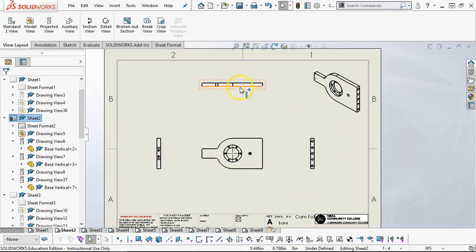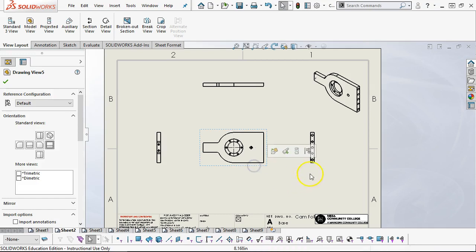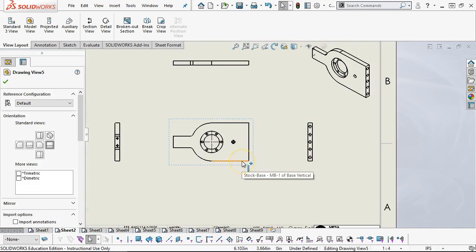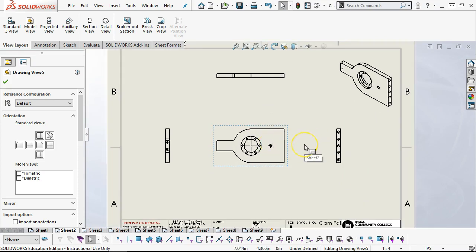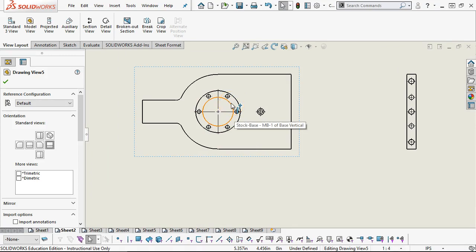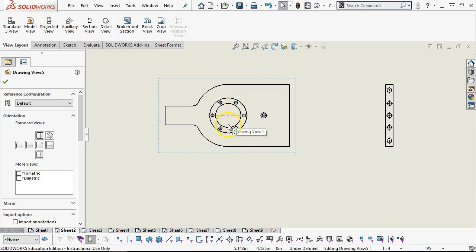All right, so when we're thinking about this, the primary datum, even though our datum simulator would be one of the larger faces, the primary datum still is where this connects to its mating part, the mirror piece. So I would think that this edge would be A. We could pick an arbitrary for B, or through the center of the bore as a B, and then maybe the, let's see, which one would that go to? Yeah, I guess one of the faces, so that we could have a B, and then in the counterbore, or the little spot face that the housing sits into, we could pick up a parallelism with that. All right, and then our basic dimensions really come back to the center of this bore in relation to A.